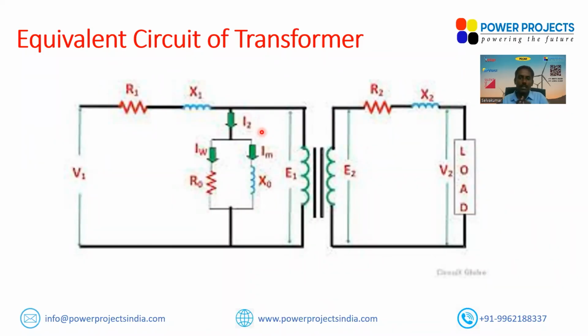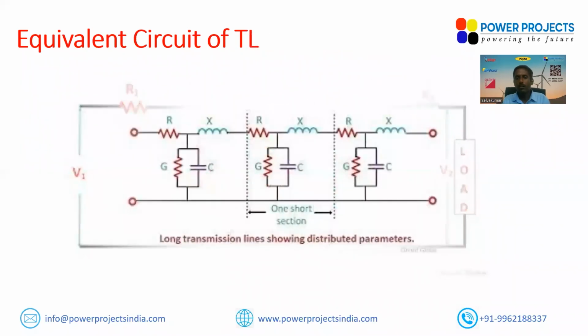So when you are asking for an equivalent circuit of the transformer, most importantly you need to ask what study you are performing. A nominal pi model might be sufficient for some studies. You may need detailed modeling of the transmission line using distributed parameters for some studies, and even that may not be sufficient.